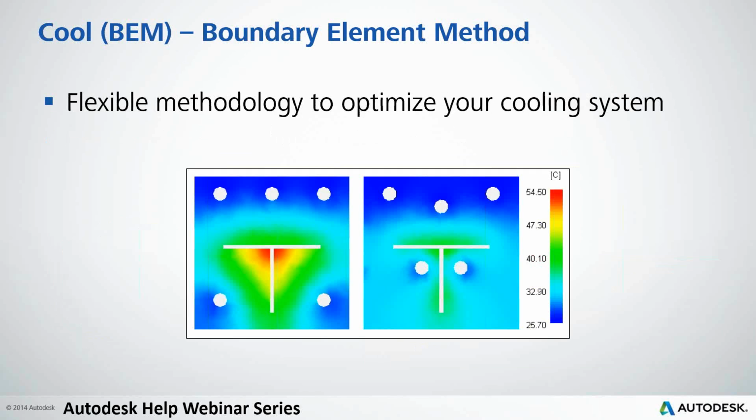One of the really nice features of the boundary method is that we don't mesh the tool. And because we don't mesh the tool, we are very flexible. In a very flexible way, we could move the cooling channels, and that allows us to optimize based on what-if scenarios: what if I move this line a little bit to the top, and to find out how we could reduce the amount of hotspots and the temperature on these corners that usually get a little bit warmer.